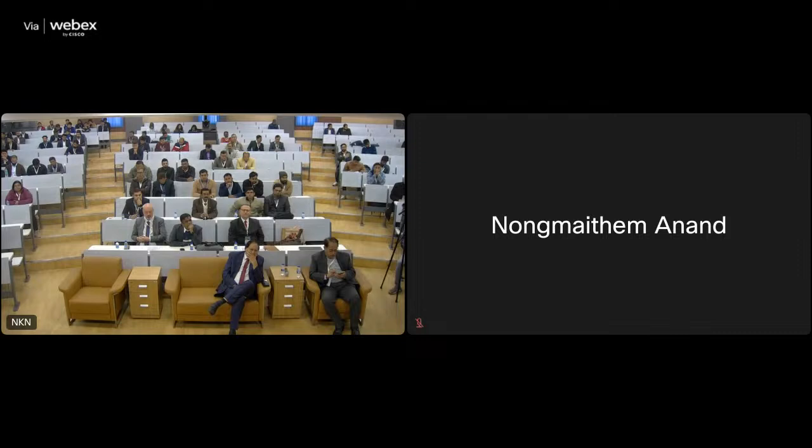Now, the range of Q which I have considered for this study. In this slide, I am just discussing the basis for why I have selected that particular range. Pre-grouting, as has been emphasized, is generally carried out in poor rocks having Q less than 1. In tunnels, little or no blasting effect is expected on rock masses with Q less than 1 because they are already highly jointed. So the rock mass is not going to be disturbed much by blasting. Therefore, Q less than 1 is not expected to be affected by the blasting.